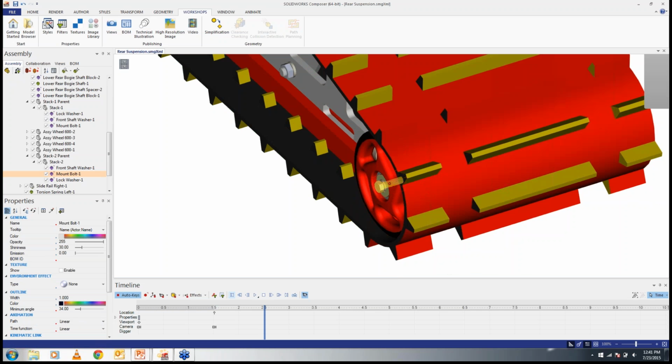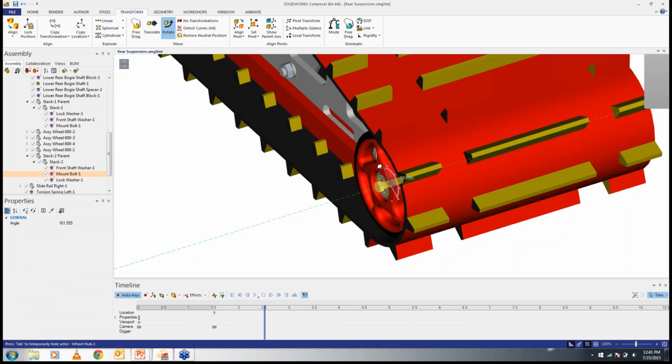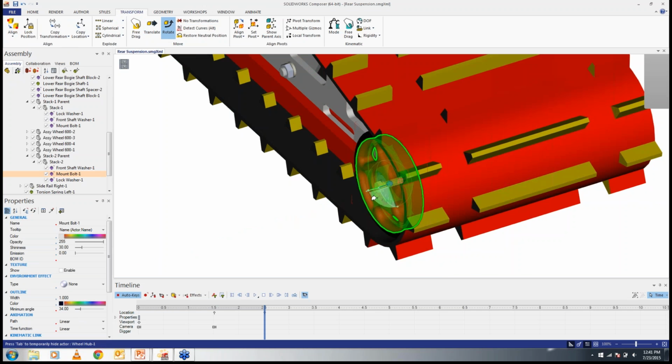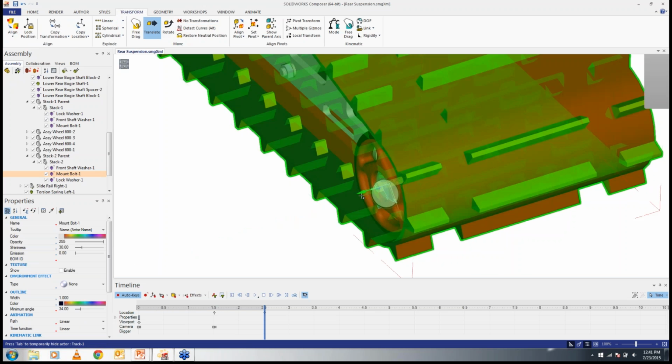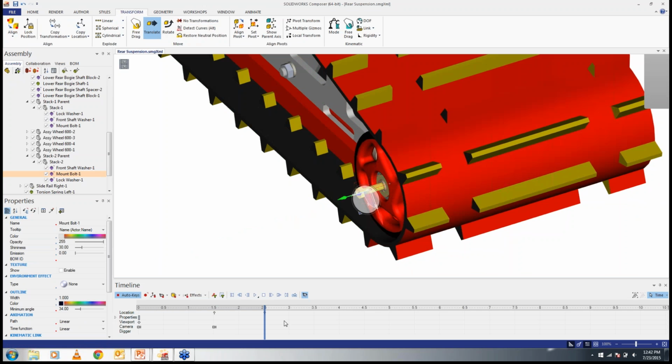Move to the next, and in the transform tab, what we have is a rotate. So I'll rotate it by around 160 degrees. Also, I'll translate it just outside the assembly, so that during the thread it translates by the thread length while rotating.